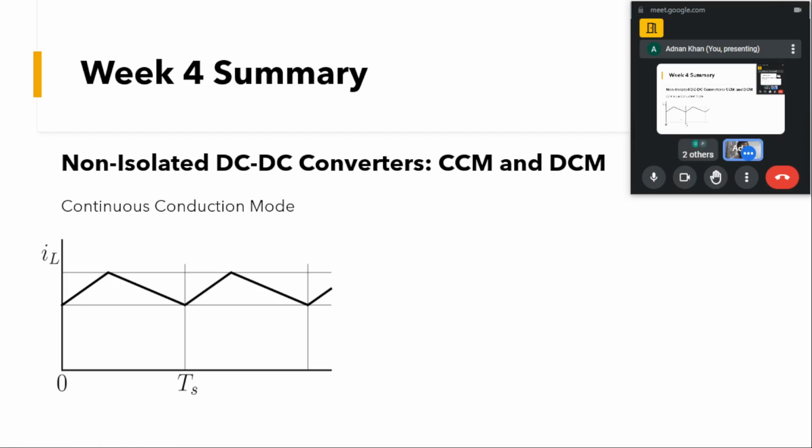If my current is zero, there is a discontinuity in the current. Let us take a buck converter example. As you know, the current through the inductor has a ripple. You can see the current in the steady state in case of a buck converter has this shape, and you can see the current is continuous in the steady state.